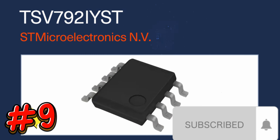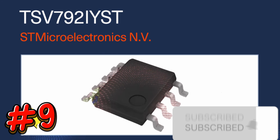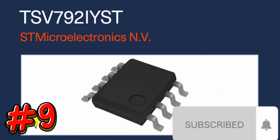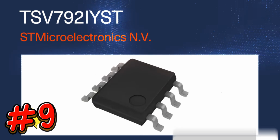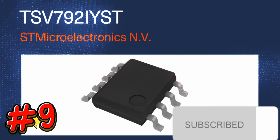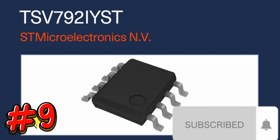The op amp can operate from 2.2 volts to 5.5 volts single supply with a capability to handle an output capacitor of up to 1 nanofarad and is fully specified on a load of 22 picofarad, therefore allowing easy usage as an AD converter's input buffer.